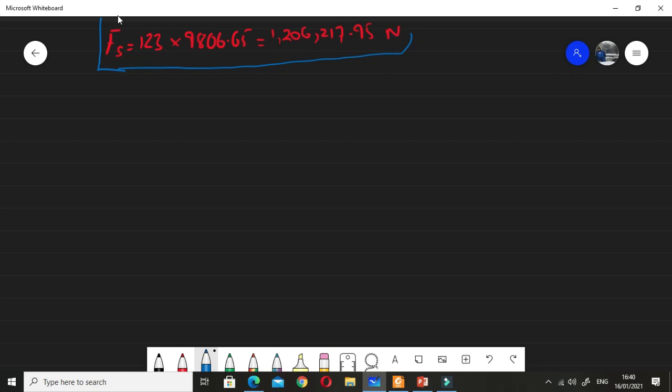We will first write down the data: we have an initial diameter of 60 millimeter and a final diameter of 30 millimeter. We have the die angle of 45 degrees, the strain hardening exponent for aluminum is 0.2, and the flow curve constant for aluminum is 175 megapascal. These two are the values for the aluminum material. If we select a different material, these values will change depending upon the material we are using.